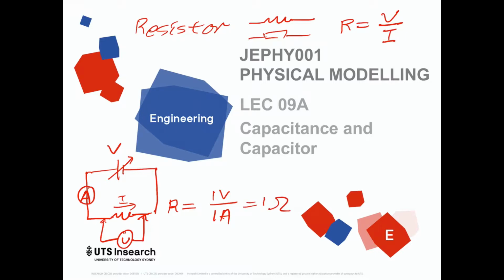It means 1 ohm. Now, if you have another resistor which requires 2 volts for 1 ampere, it means the second one will have higher resistance. It just means 2 ohm. So you see the meaning of ohm. It means how much voltage, potential difference, across the resistor, in such a way that you can push 1 ampere current through the resistor. The higher the voltage, the more energy you need to push it through. It means the resistance is higher. So this is the physical meaning of resistors.